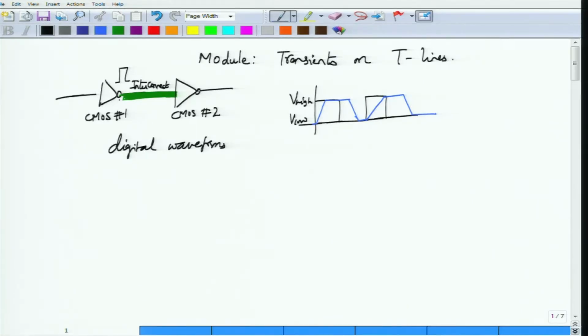interconnects, obtained at the output of one component which we call the source and to be transported to the load, are switching like this. Okay, we will initially not consider the pulse excitation. We will assume initially that the transmission line or this source was not having any voltage initially, and at some t equal to 0 it has arbitrarily changed its value. Okay, there is a step waveform that is launched on the transmission line.